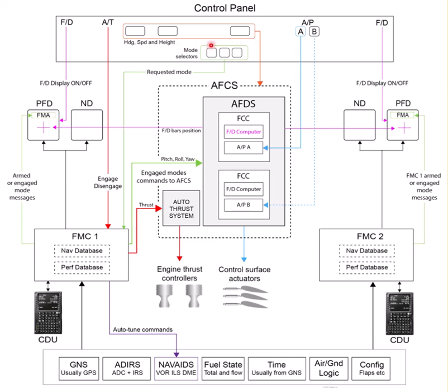So you can see that information is going to go into the auto flight and direction system to the flight director, depending on whether you've pressed heading or a speed or an altitude or whatever it is you're after, even LNAV and VNAV. But a lot of the time, of course, this was used for approaches for the localizer and the glide slope.